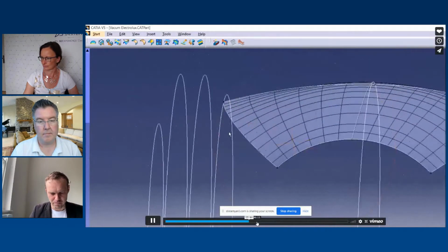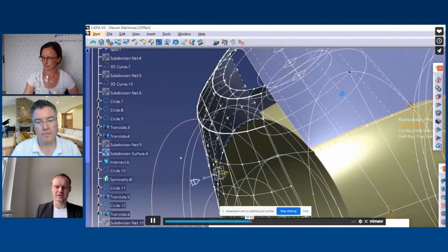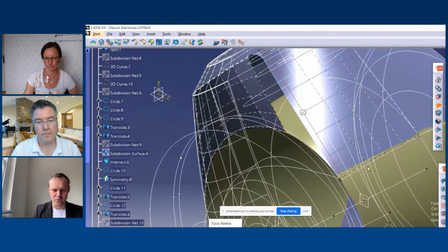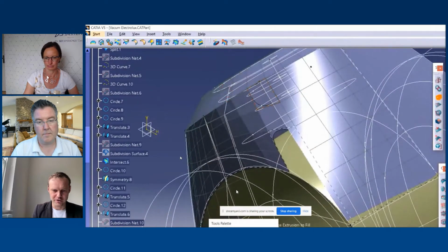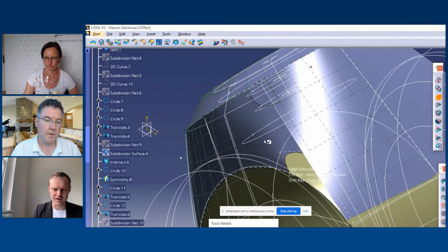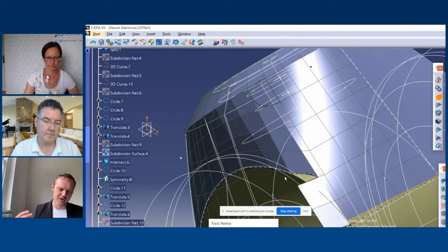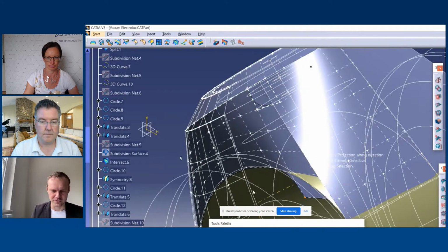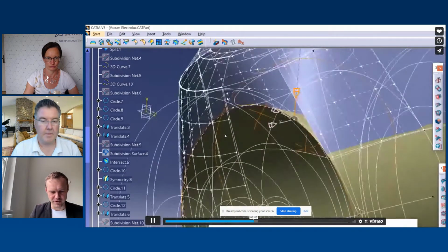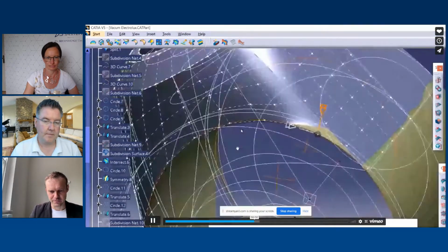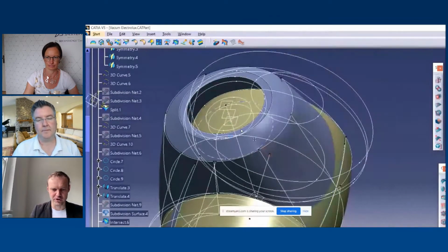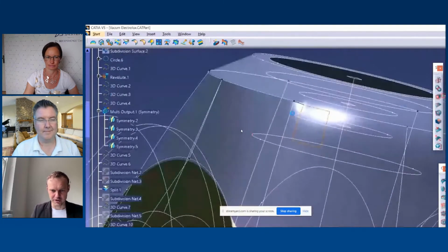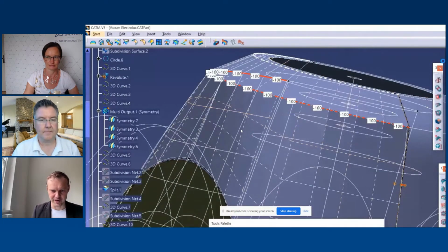And as I go, I start to add more complex surface to these guide curves. And that's how the model is precise. I already know that the proportion is right, and then I keep adding those details. So this is basically how you get very quickly from the proportion model to the styling model, a very detailed styling model.